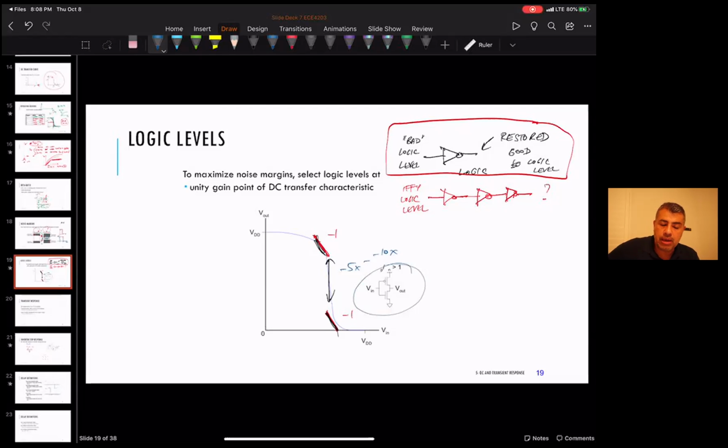They don't make very good analog amplifiers, but you know, in a pinch. But look at this, this is sort of a bad situation. If you have noise on your input, you're amplifying that noise on your output. So basically you want to stay away from this region and you want to be here and here. So you define it where you go to a -1. Past -1, past here, you're getting a gain higher than 1, and at every layer of logic, you're increasing the amount of noise you have. So anyway, that's how we define it.